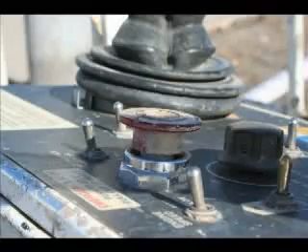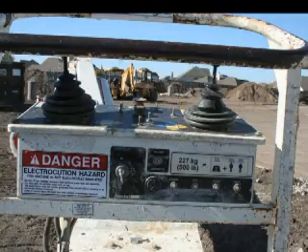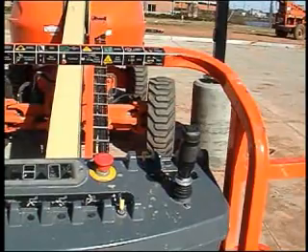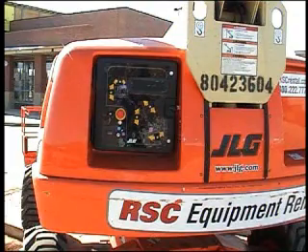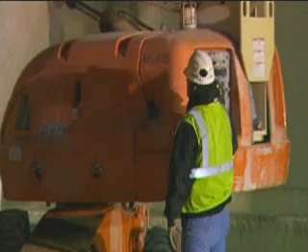Aerial work platforms must have both platform and lower controls. Platform controls must be in or beside the platform within easy reach of the operator. Lower controls should be able to override the platform controls, but should not be used unless permission has been obtained from the personnel in the lift or in case of emergency.